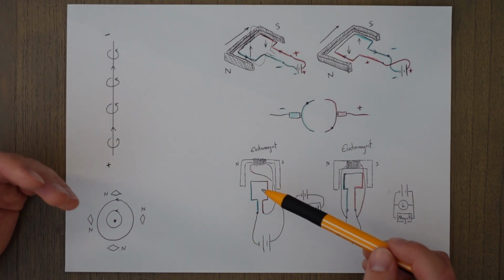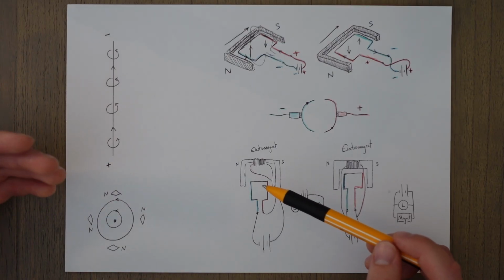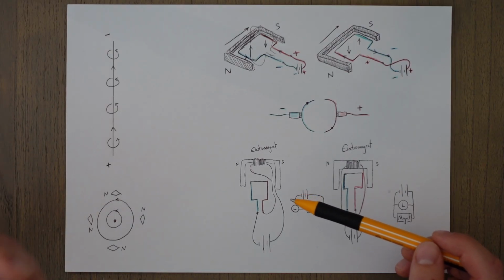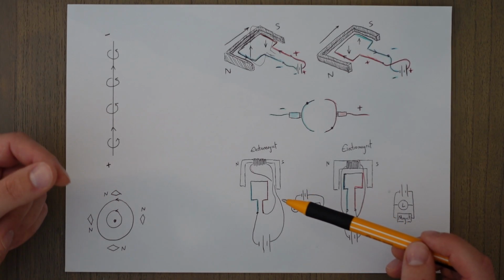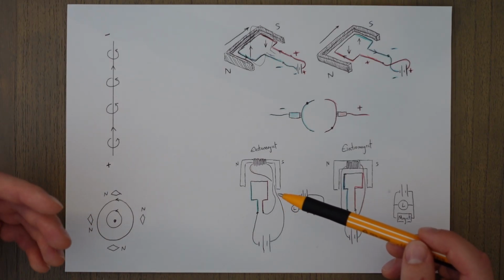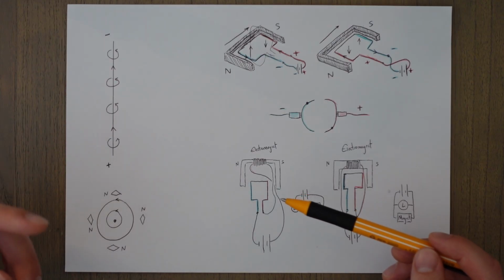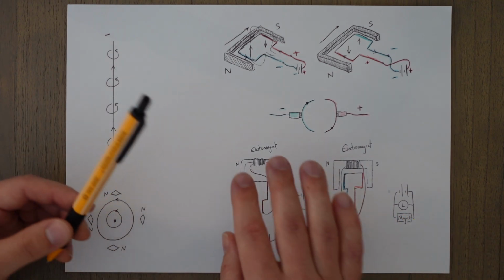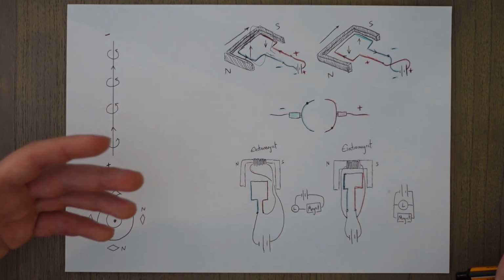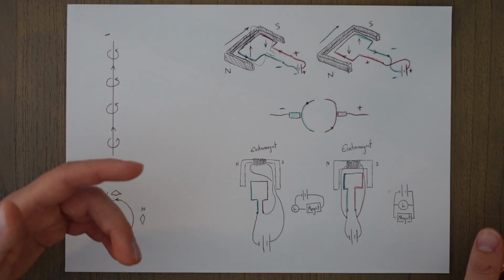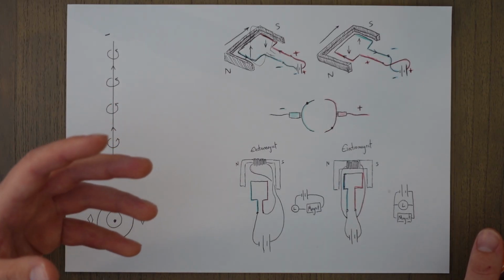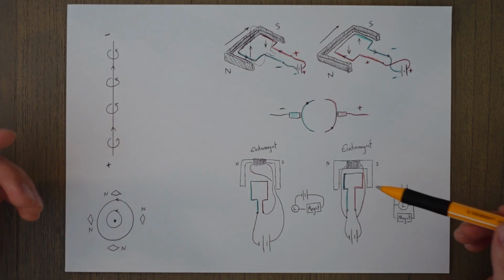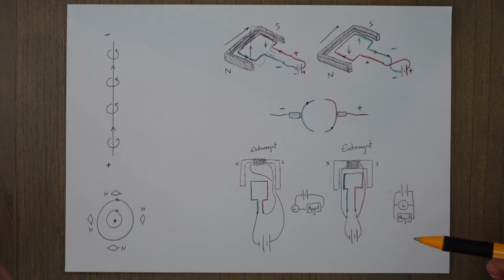We use a stator with low resistance, a low resistance electromagnet, and this creates a high current. This high current produces a strong magnetic field in the stator, and it does so immediately, which means we get a high starting torque force. The motor, however, can overspeed unless controlled carefully through current regulation or by restricting the torque output through mechanical brakes and things like that. This is a common setup for things that require a short, sharp burst of power, like a starter motor on an engine.